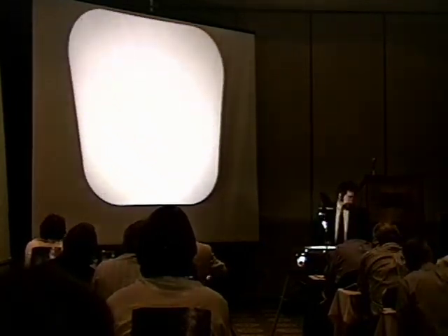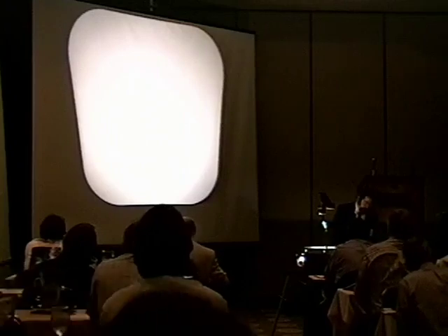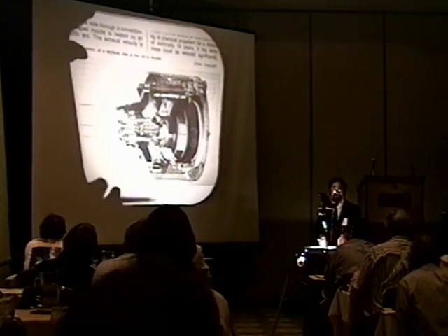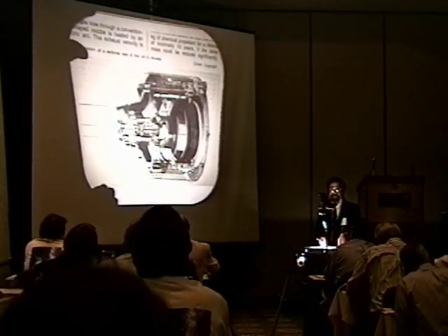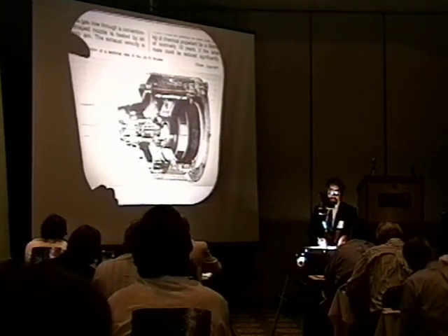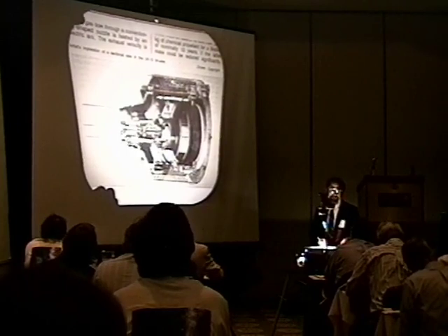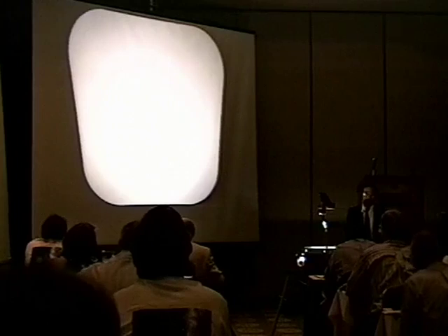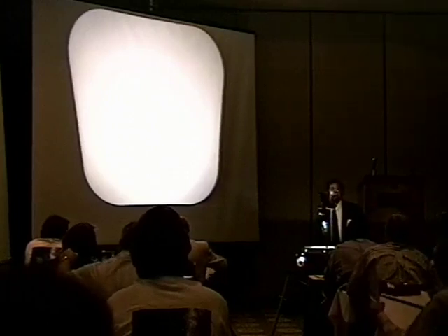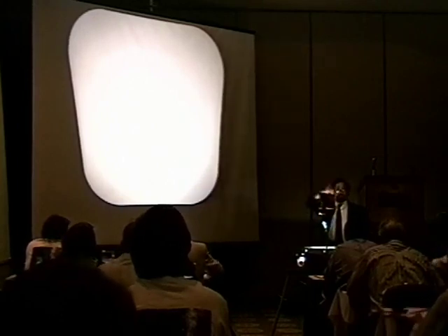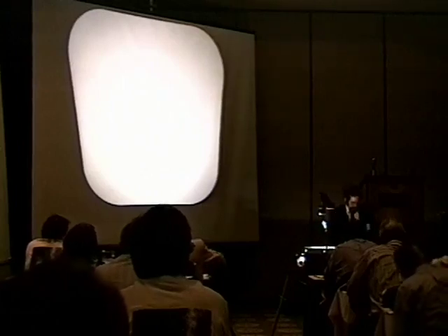It's an ion engine. Basically, you ionize mercury or cesium or argon, and here's another view of it. So you can just hook up electricity to this high voltage electricity source in space and go with very low thrust to weight, less than 10 to the minus 4 ratio of thrust to engine weight, and go out there with very high efficiency. The problem, by the way, with ion engines is that you have to go very slowly. The acceleration is low, and therefore to go out of Earth orbit to get to Mars, you have to spiral around for months. But you still get there.